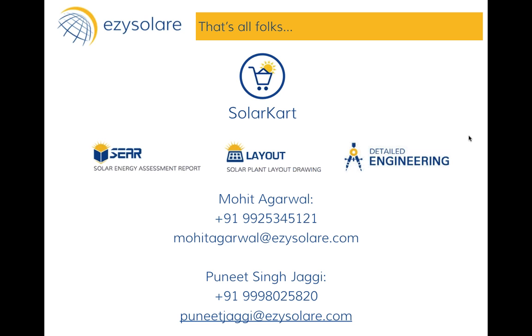So the question is, what is the importance of string monitoring, and why not array monitoring to save a lot of capex and spares? This question is by Karthik Raja. The question is actually extremely intelligent. First of all, what parameters can you really measure in a power plant? Obviously, you can measure the net generation at a meter level. You can also measure the uptime and the generation at the inverter level. Lastly, there are lots of strings which come as an input to the inverter, right? So you could measure the generation at the string level as well.